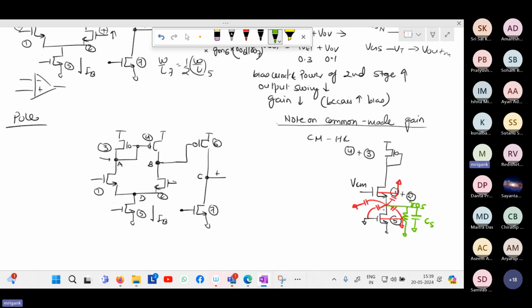As a result, common mode gain will increase at higher frequency. But then also on the upper side, you have additional poles because of the capacitor. These poles will again try to bring it down. So it will increase, but then the two effects will try to cancel out each other. To some extent, it will balance out. As compared to the DC value, it will increase initially and then stabilize to some value.